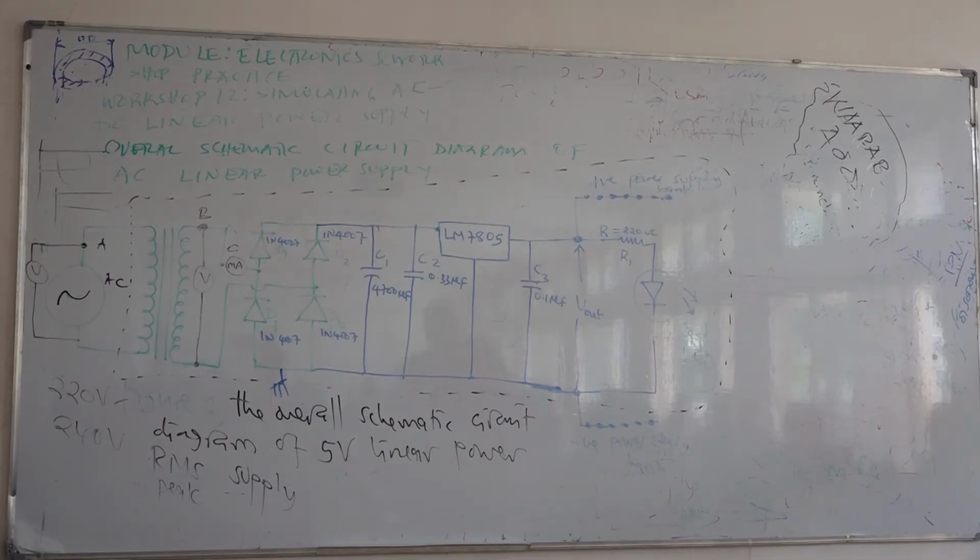That's why we need to know the formulas. That's the use of the formulas and the equation. Because remember, the AC voltmeter measures the root mean square value. But in case you want to change the AC into DC, you need the maximum value. How can you achieve it? You have to measure the root mean square value and then use the formula to convert it to maximum voltage.